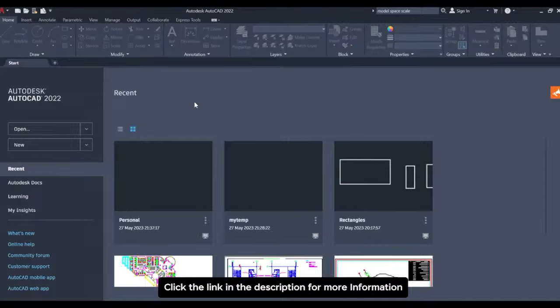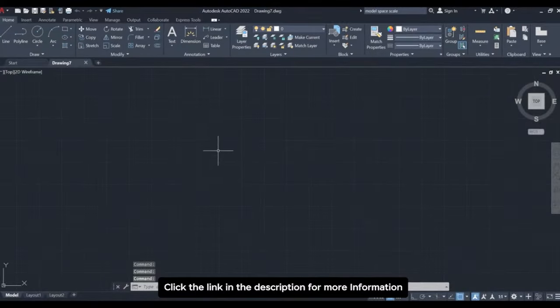Lastly, we'll have a look at the function keys in AutoCAD. So let's take a new drawing, which is based on our personal template. And over here, let me draw a simple line and let me explain all the different keys that are present over here. So I'll enter and the limits are set. That's why I'm not able to draw outside the boundary. So let me just turn off the limits. And let me draw a simple line for you first.